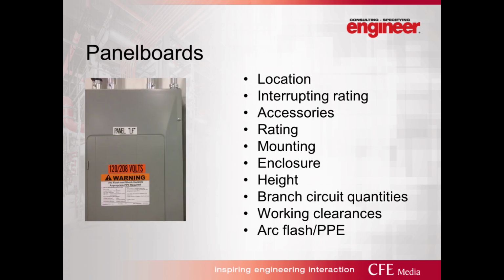Panel boards. There are many options to look at when specifying panel boards. There are locations, interrupting ratings, accessories, mounting, and make sure working clearances are met. So make sure you consider where you place the panel to assure you meet your minimum voltage drop requirements.